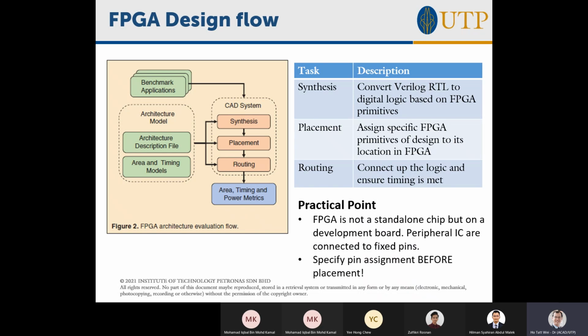In an IC, for ASIC, the placement process is actually, you've got a particular area where you can put that logic gate: you place it here, you place it here, you place it here, because you have to arrange the logic gates somehow onto the chip, right? So the placement step for ASIC is doing that. And then the routing is the final step, where it's actually creating the wires to connect all these logic gates up so that they obey your design.